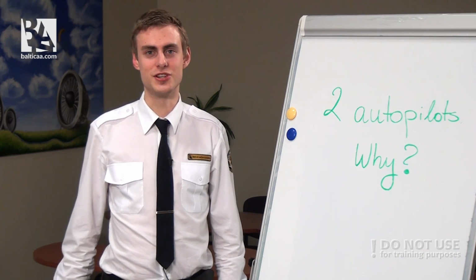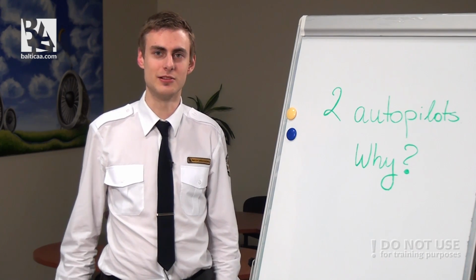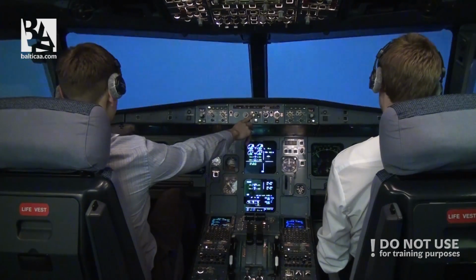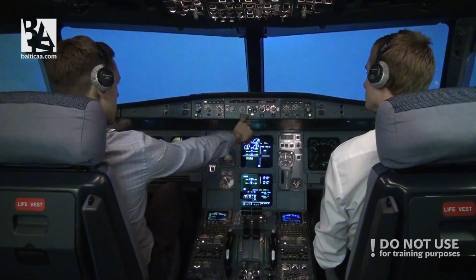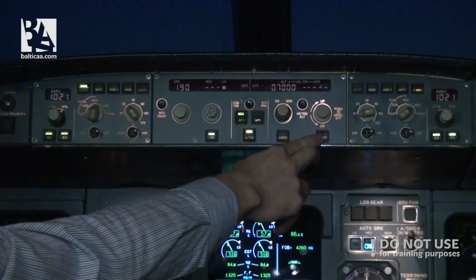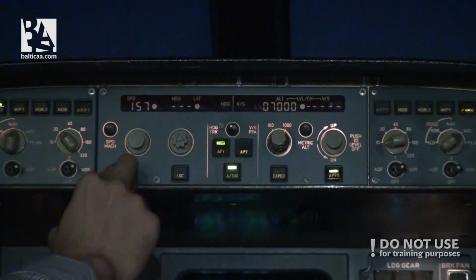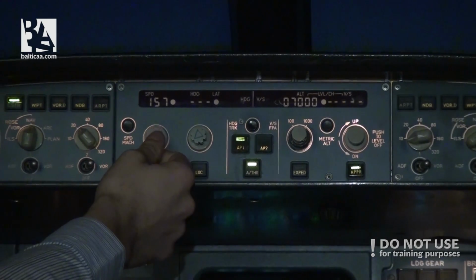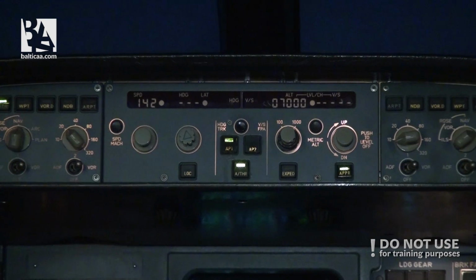Everything in civil aviation should always be redundant to minimize the risk of a major technical malfunction. From structural load-bearing redundancy, emergency oxygen supply, to multiple hydraulic systems, we are striving to have 2 or more components of everything, even pilots. If you are flying in a large airliner, you will probably have 2 or even 3 autopilots. They are both used simultaneously in an autoland and are required for any automatic precision approach.